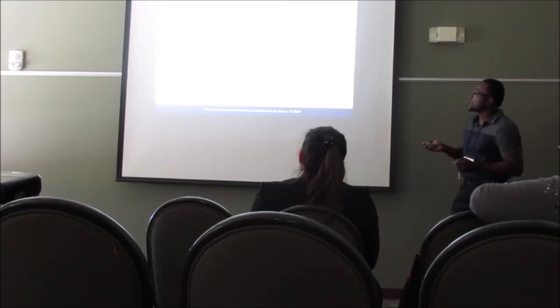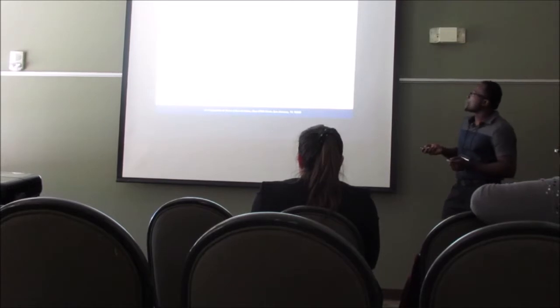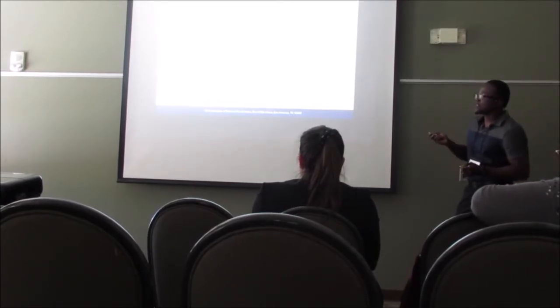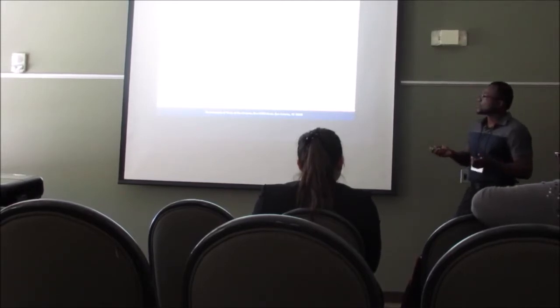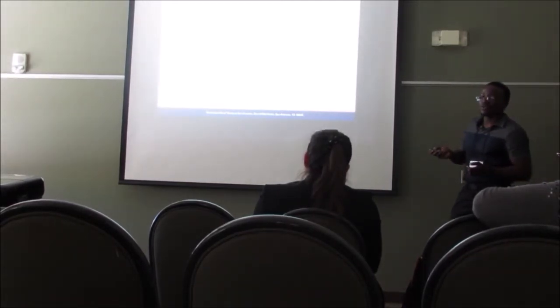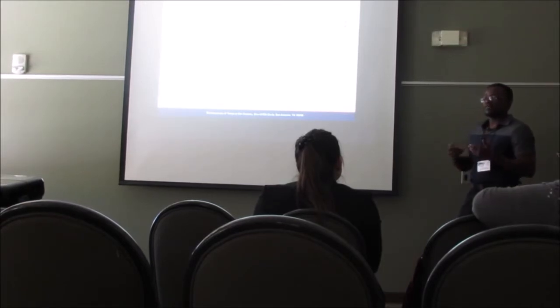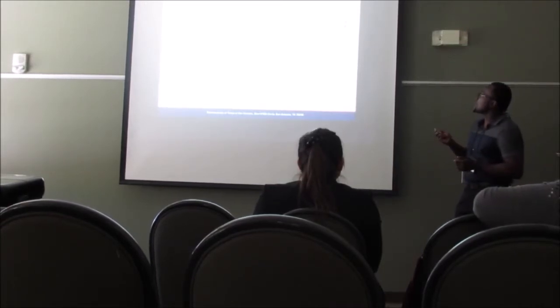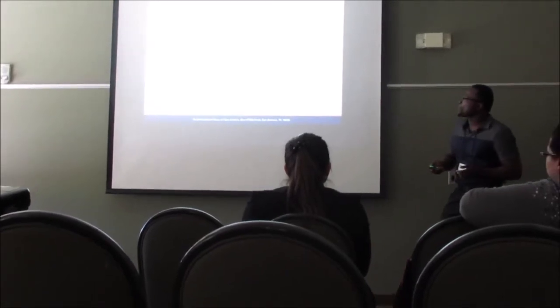When we look at the other type of regular deformed bar, the number 3 bar, we saw the same type of behavior, and the first flexural crack occurred around 3,000 pounds. And here we got a large deflection because these regular bars have a lower yield strength, so they're more flexible. That's why we're able to see a large drift ratio in these bars. When we compare with the spiral bar, because these bars were very brittle, we're not able to get a large deflection out of it. But in terms of strength and behavior, it was almost similar to the regular deformed bars.